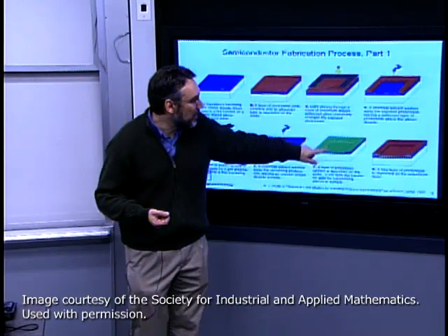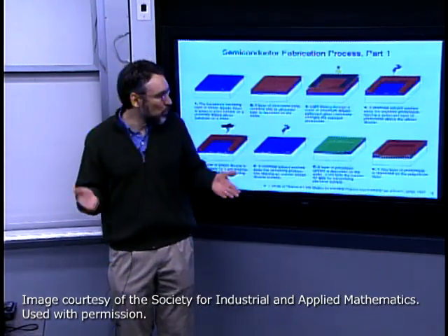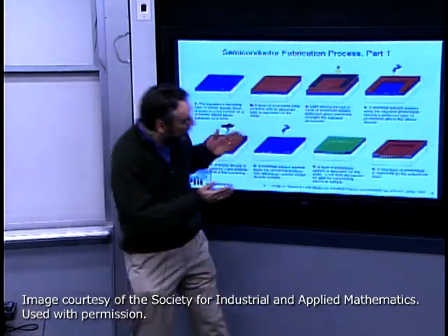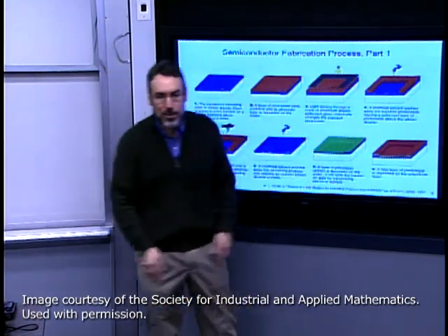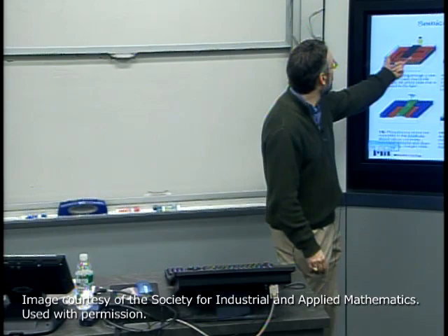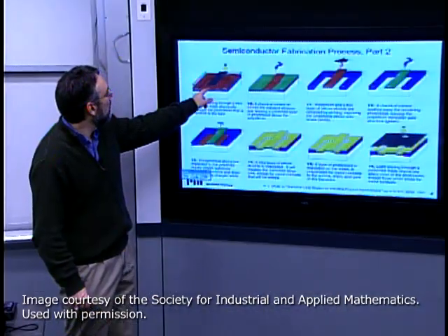So we've deposited that. Recall, what geometry do we want? We want this thin gate electrode, so we're going to do a photolithographic step again to do that. Deposit photoresist, expose. In this case, here again, another positive photoresist case, so we're blocking this structure.